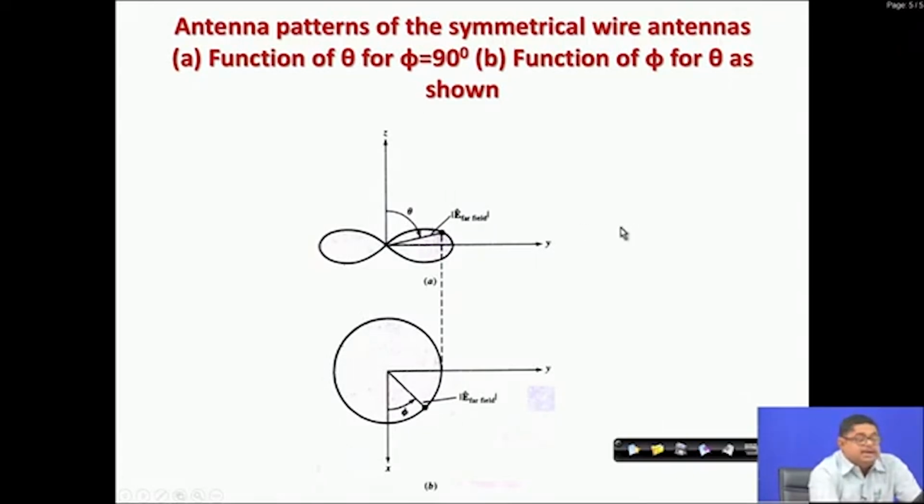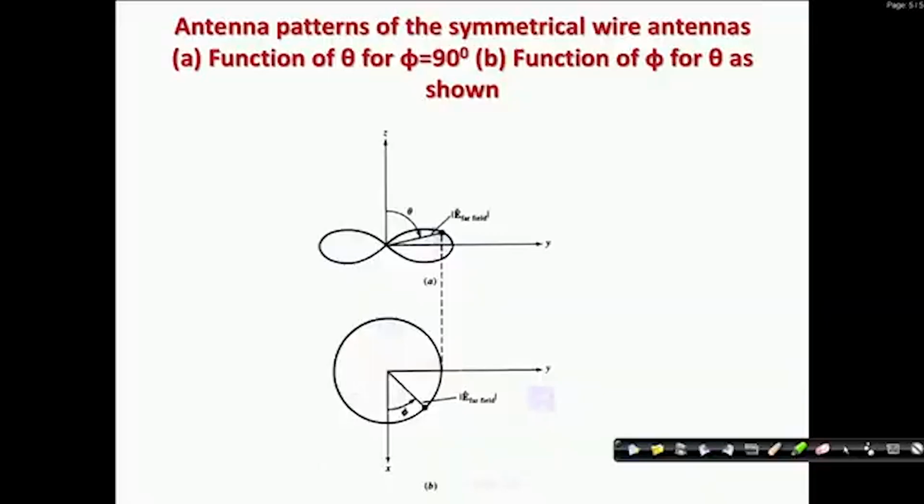Now, only to rectify this, if instead of a single antenna we use two antennas or more and more number of antennas, then this problem can be rectified. That is why you will see that these communication antennas are sealed in a box. If you look at the cellular telephony base station antennas, you will see that they have a long box. If you open the box, there will be antennas; they use something like patch antennas, but as an array of patch antennas. Instead of patch antennas, they could have used dipoles also. In some of the stations you will see a number of dipoles together. So, that array antenna is to shape the pattern, so that the interference, etc., can be avoided.